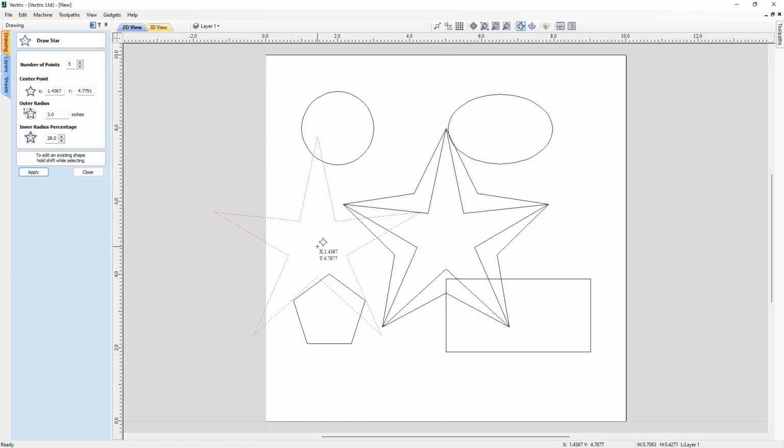And again, we can use the click option to actually drop that in, and whilst it is highlighted, we could actually change some of these options. Let's say I wanted to make that 2 and 75, and then here you're getting a sort of pentagon shape here. Again, let's just go here, 50, apply, and you can see how easy it is to make those changes.